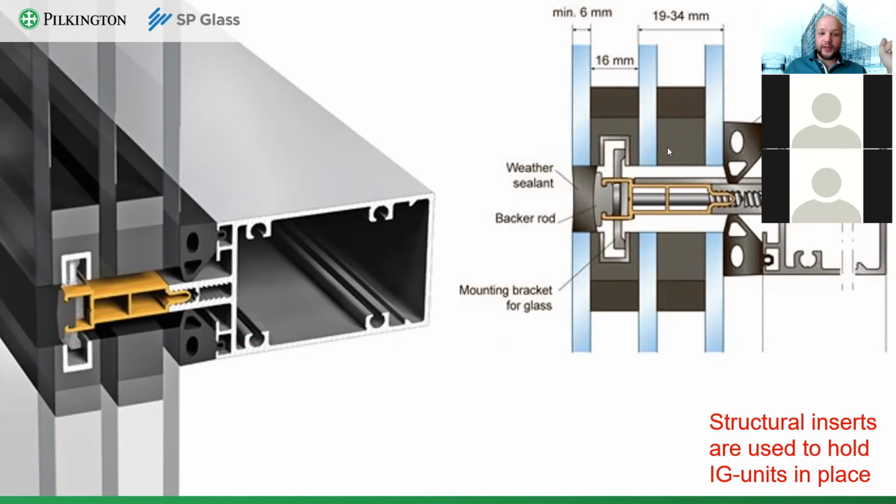Is this a triple glass? Yes, this is. Sorry, I've used a different type of pictures just to demonstrate. For the double glass, the system is the same. You just have a different length of the screw and the facade system. The principle of holding the structural glazing is absolutely the same.